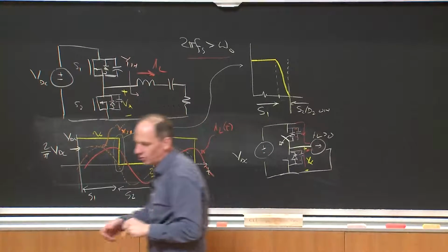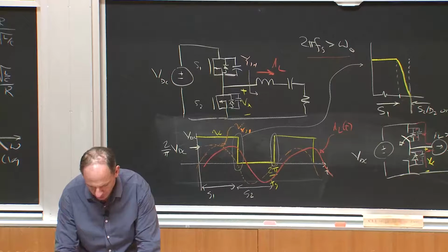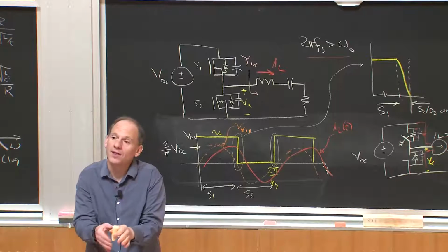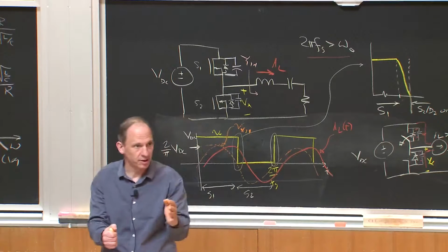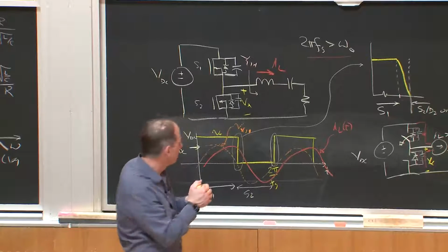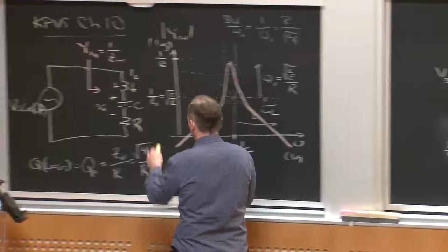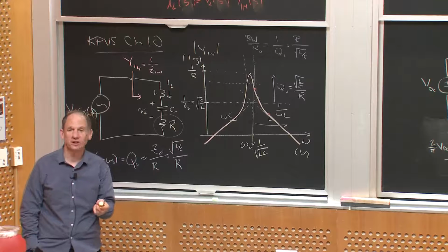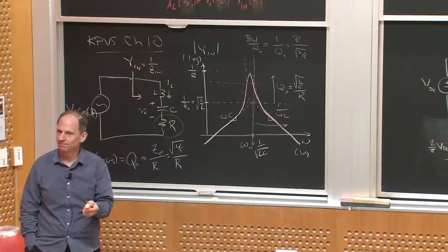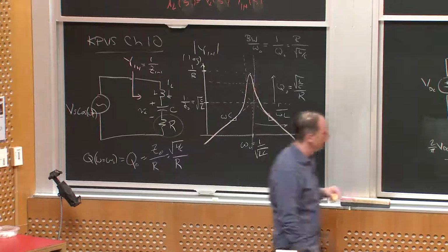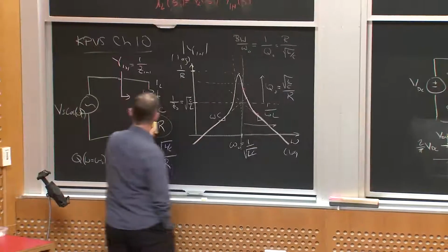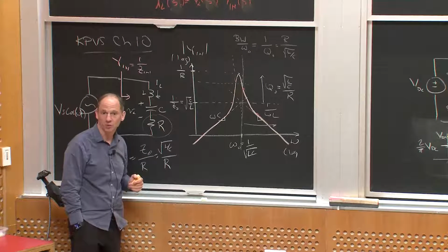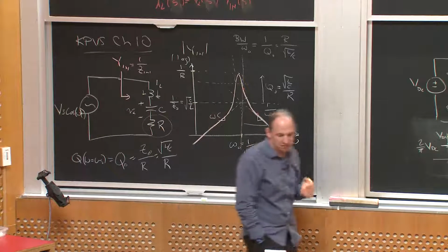All right, so we can get 0 voltage switching, and by doing that, we can go at pretty high frequencies. And then we can use frequency modulation, frequency control, to control the power into our load. Now, what is our load? Well, I haven't said what this load is. It could be any number of things. It could be, for example, the equivalent resistance of an induction heating load. And thereby, by modulating frequency, I modulate power, and that's how an induction heater can work. And I can run at high frequencies because of that.